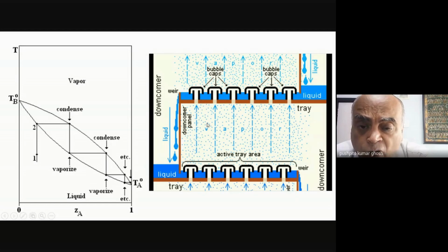But because we are talking about relatively low differences in boiling points, obviously the efficiency with which I do my fractional distillation is extremely important. So in the old days, when initially Linde was doing his work, he had these porous trays. These are trays, and there are numerous such trays through the height of the column. So effectively, what are you doing? At the bottom there is liquid.